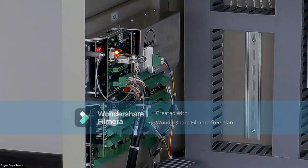So gentlemen, even if the scavenge control unit application was installed on this MPC, if you notice, now it is making a download because we asked to perform a force download. The DIP switch number 4 is in off condition. Clear?